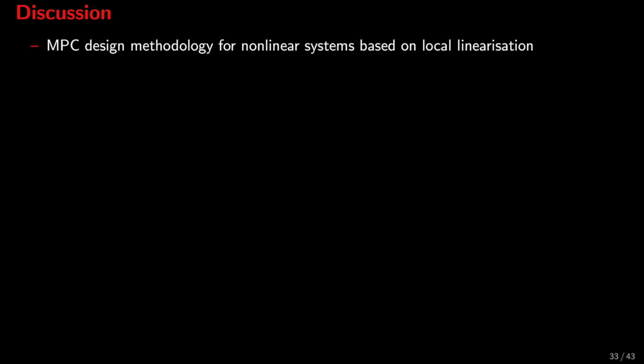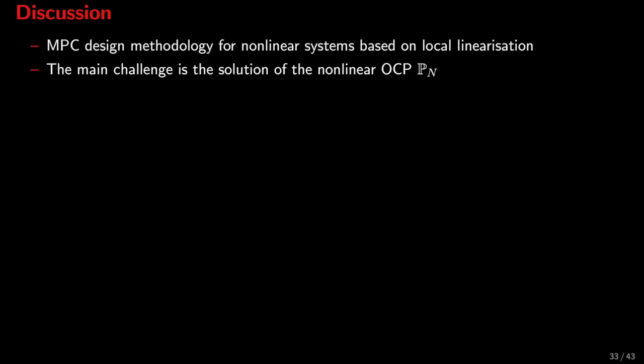that we can choose. We have stated a design methodology for nonlinear systems based on the local linearization, on the linearization of f at the origin. The main challenge remains how to solve the nonlinear optimal control problem that we have to solve in real time. So every time we need to use MPC, every time we need to compute a control action, we need to solve a non-convex optimization problem, a nonlinear optimal control problem that involves nonlinear dynamics.